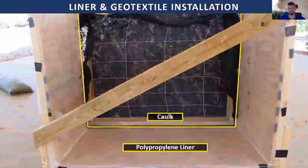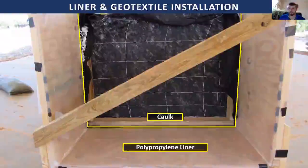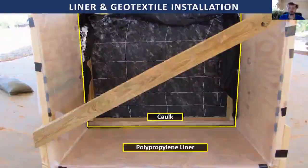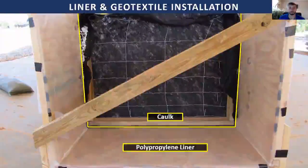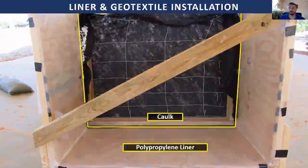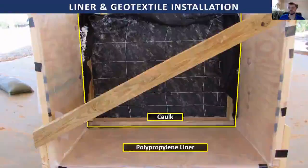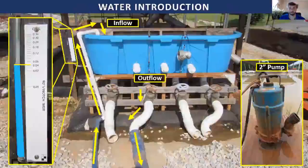When we install the geotextile, we line the wooden box with a polypropylene liner. That way flow cannot escape through the cracks. And we also caulk the geotextile to the polypropylene liner. That way we ensure that all flow actually passes through the geotextile and that there's no flow bypass.